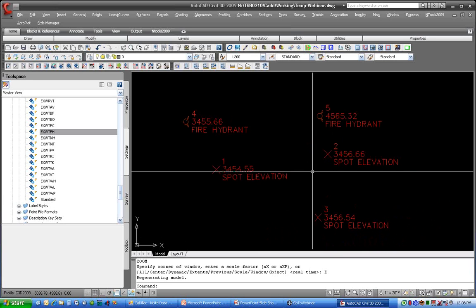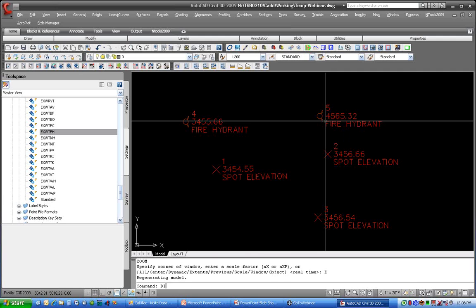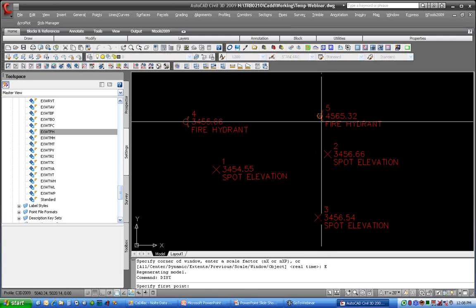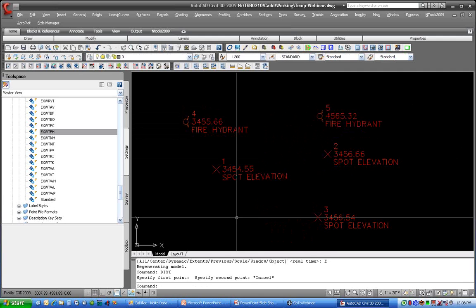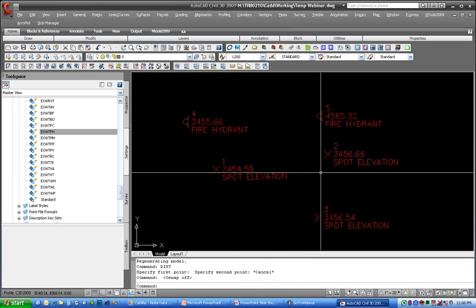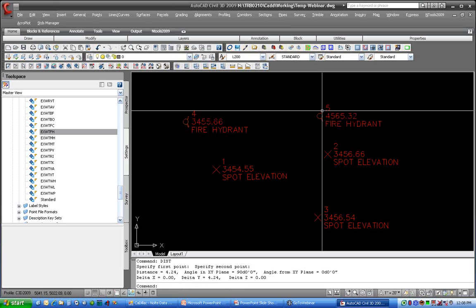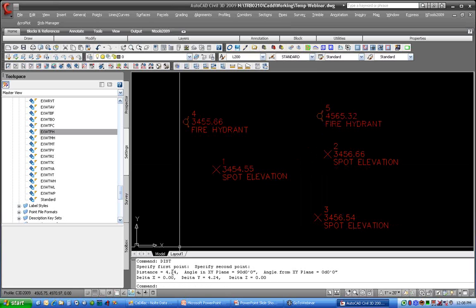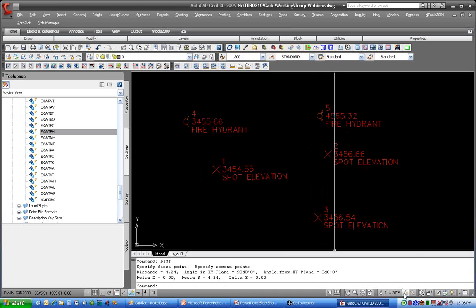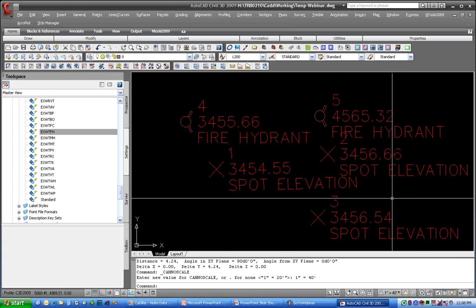All right, to show the scale component here, if I measure quick distance across here, if I go from, oops, I snap to the object. Let me turn my snaps off. And we'll see that's approximately, I eyeballed it, 4 units, so it is taking that 0.2 times my drawing scale. Whereas if I change my scale here and say I want my drawing to be 40 scale, you see everything resizes on the fly.